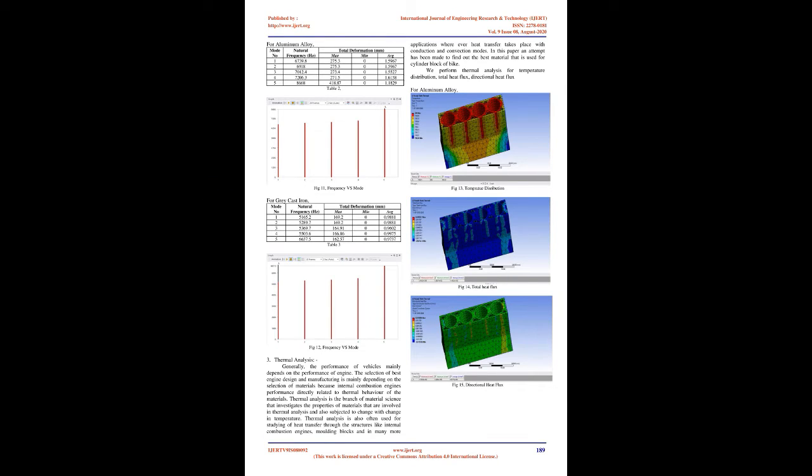The equilibrium equation is solved either by a direct or an iterative solver. By default, the direct solver is invoked, whereby the unknown displacements are simultaneously solved using a Gauss elimination method that exploits the sparseness and symmetry of the stiffness matrix, K, for computational efficiency. Alternatively, an iterative solver using the preconditioned conjugate gradient method may be used. While the direct solver is very robust, accurate, and efficient, the iterative solver is sometimes superior, in terms of speed, for thick-walled solid structures. The structure's behavior is linear and must obey Hooke's law.